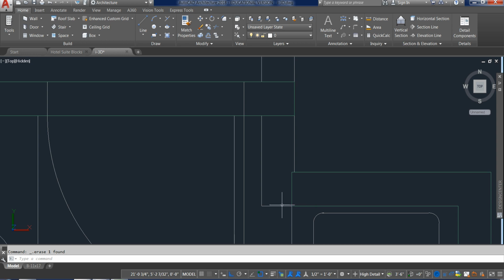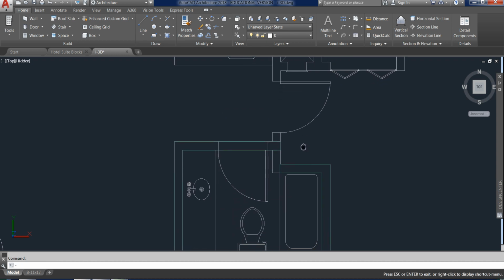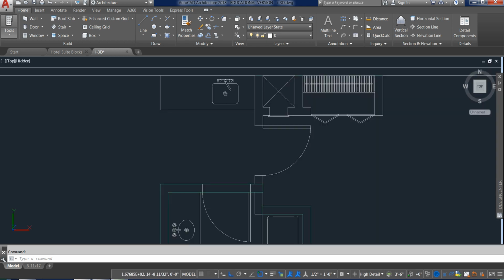And I need a wall going from here all the way up. So that will carry that wall through. But do you see how this wall goes all the way through the door? We can pop the door openings in. So if I stop the wall and then try to put a door into an empty space, I might actually get the door to stick there. However, the door won't have a header. It won't have anything above it. And the doors are only going to 7 feet. And right now, the walls are going to 8 to 10 feet. So that really doesn't work.